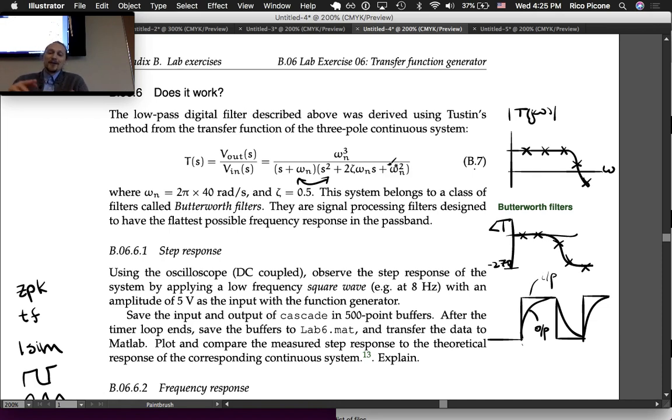But you can do pretty amazing stuff with just the simple building blocks. If you can measure analog inputs and you can write analog outputs and you can compute filter or controller outputs, digitized versions of a continuous one, easily, then it essentially allows us to go from a theoretical controller to an actual controller, which is what we'll do.